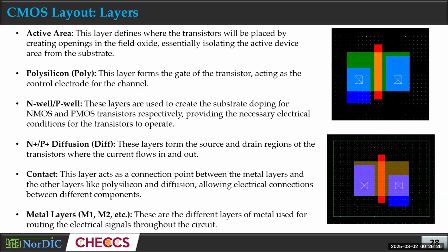Okay, so you can see the advantage of using tools. Again, like in simulations we had built-in transistors, where we just drag and drop the PMOS and NMOS in the simulation. Similar thing we can do for layout. So this is the NMOS and this is the PMOS layout. So we have this ready. We will just drag and drop and connect like in the simulation. Okay, so this makes our job easy, right?